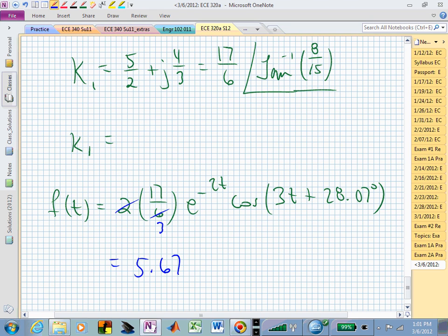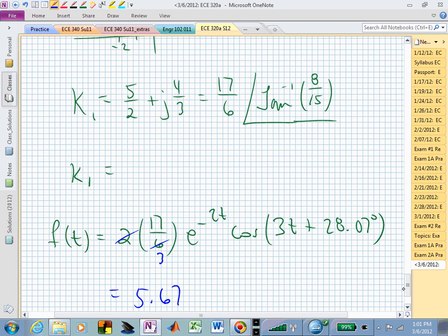Yes, so if you put the right signs on your real and imaginary part, depending on the brains in your calculator, it may give you the proper quadrant of the angle. A lot of times some calculators just give you an angle between plus or minus 90, and it may not give you the proper angle. So I always recommend that you sketch your piece and see what this particular set of horizontal and vertical gives you for an angle.